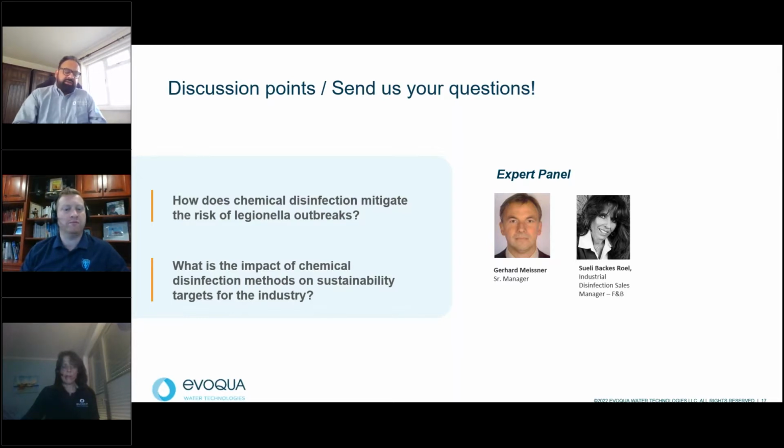Yeah, so with the use of chlorine dioxide as opposed to other chemical disinfection, the effectiveness is mainly seen on the biofilm. When it's a new plant, it doesn't allow the biofilm to form itself. But in installations where other disinfectants have been used, when you introduce chlorine dioxide, it first breaks all those biofilms that have formed.